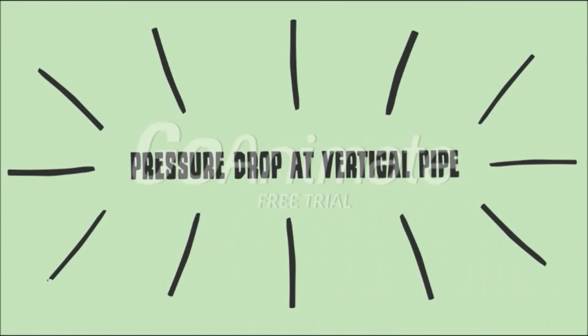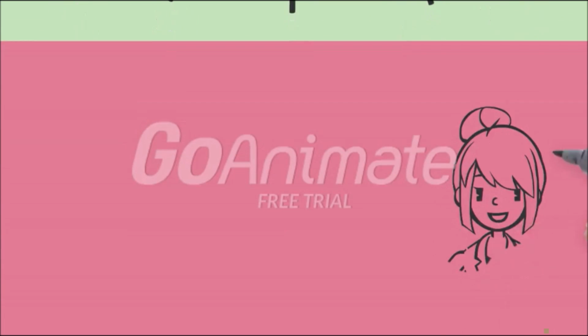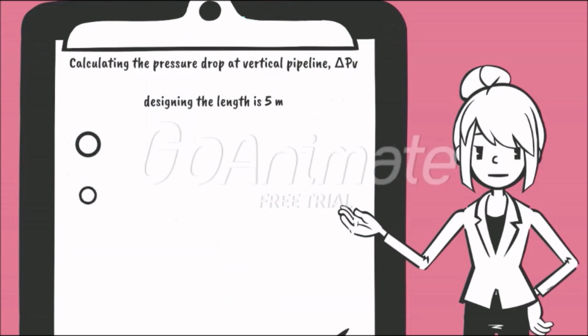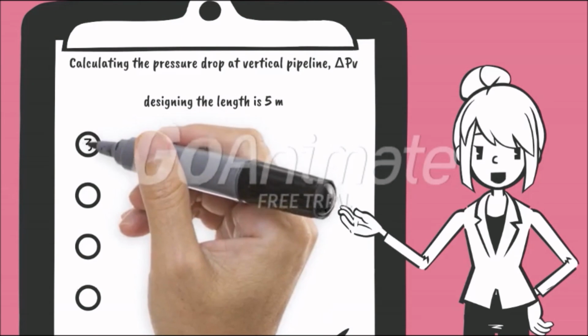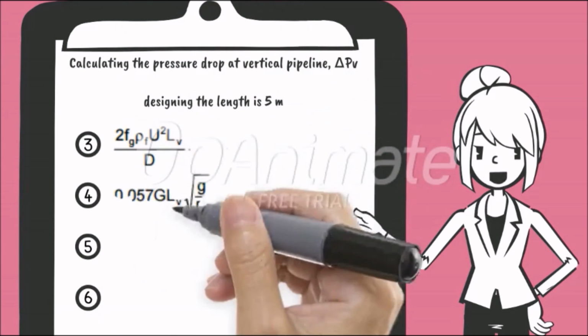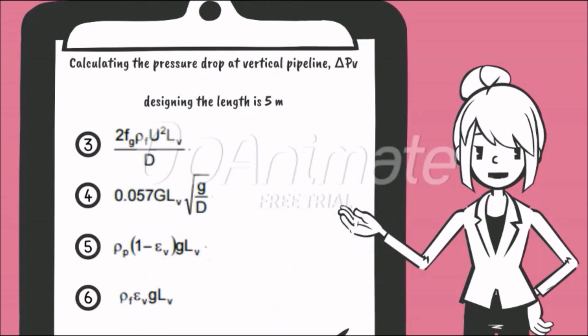Moving on from the horizontal pipeline, now we focus on the pressure drop across the vertical pipeline, assuming the length of the vertical pipe is 5 meters. The terms involved are 3, 4, 5 and 6. Terms 1 and 2 are 0 as the initial acceleration of solids and gas is done in the horizontal section.